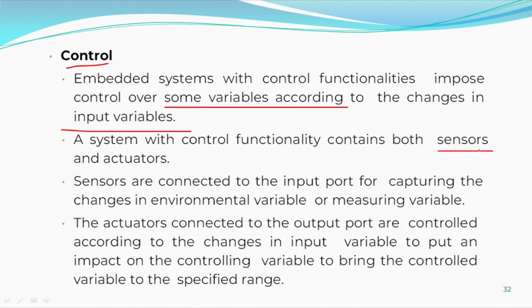So they always have sensors and actuators. Sensors and actuators are those devices which will convert one form of energy to another. What do you mean by that? If you consider sensors, then let's assume there are some changes in the external parameter that will be measured and it produces electrical signals, and if these electrical signals are passed to actuators, based on those signals this will generate some sort of action or motion, or in other words mechanical energy. So the sensor converts various forms of energy into electrical energy. The actuator converts electrical energy into mechanical energy.